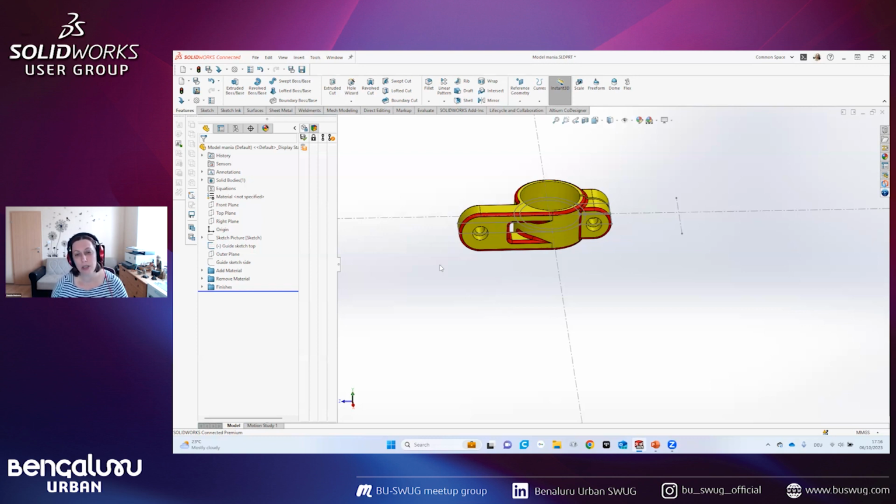But it turns out if you try to extrude just with certain contours directly from the guiding sketch, it's harder for SolidWorks to rebuild afterwards. And if you create a new sketch and convert the entities that you need, the rebuild time will be much shorter. So don't use one sketch, better use this sketch just as a guide and convert entities in new sketches. This will guarantee faster rebuild time.